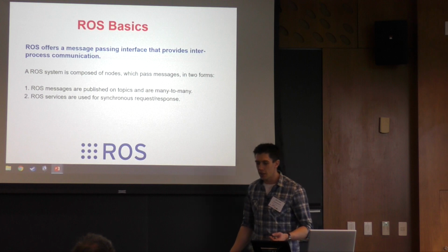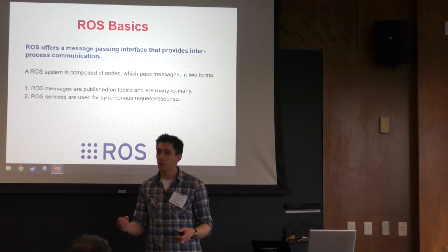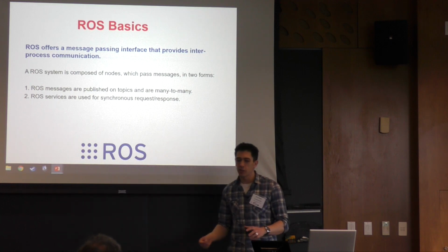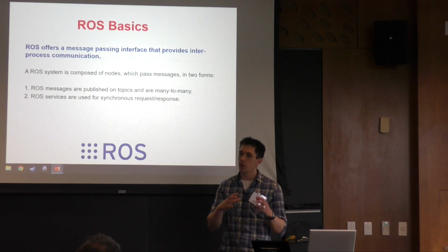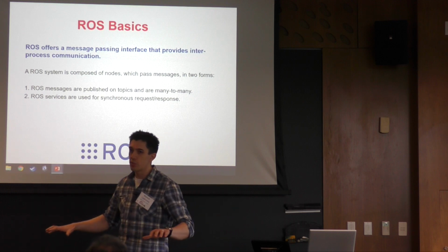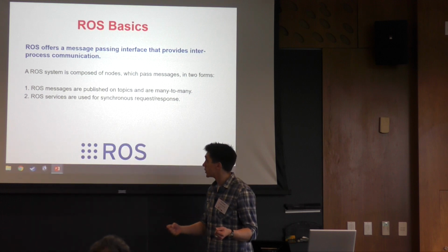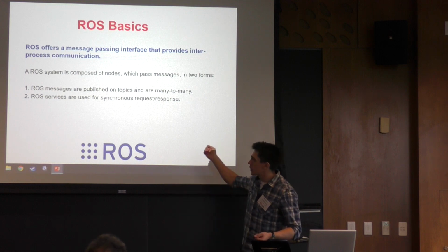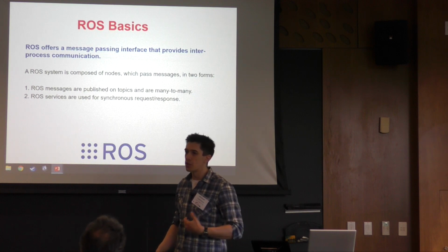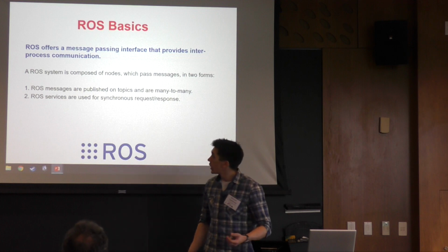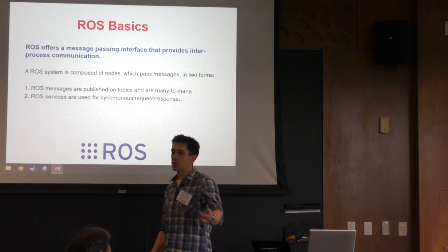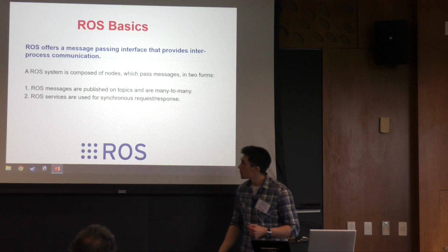Okay, so ROS is a framework for coding robotics applications. A ROS system is comprised of a set of processes which are encapsulated in what's called nodes that can run on a single platform or distributed platforms and communicate by passing messages. Messages can be passed on topics in a many-to-many communication. Any node can publish to any topic that it likes or subscribe to any topic, or as services, which are more like remote procedure calls. These will block the service until a response is sent from the other node.